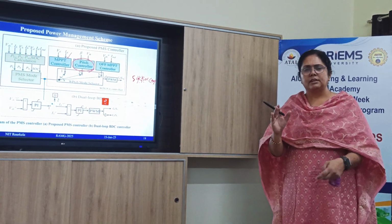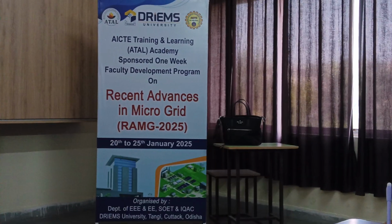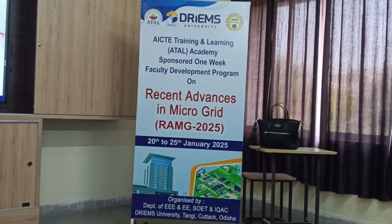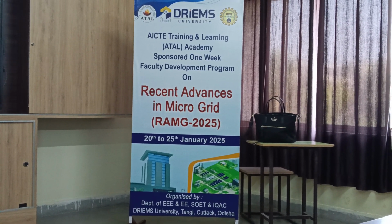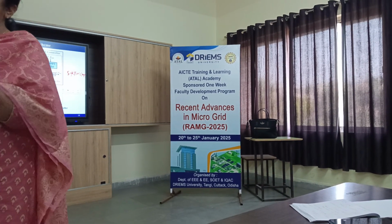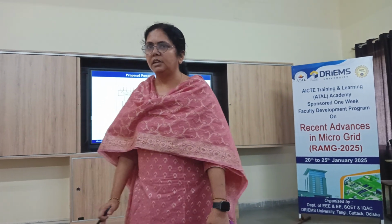When drives are there, na? This is for a pitch angle system. Each controller may have a time constraint. Yes, time constraint is there, but this is for a higher simulation, higher power rating. In a lab system, I am operating in a normal scenario, but suddenly wind speed is increasing. I am creating that scenario. So it has to switch from MPPT controller to the pitch control mode so that I can limit the power.